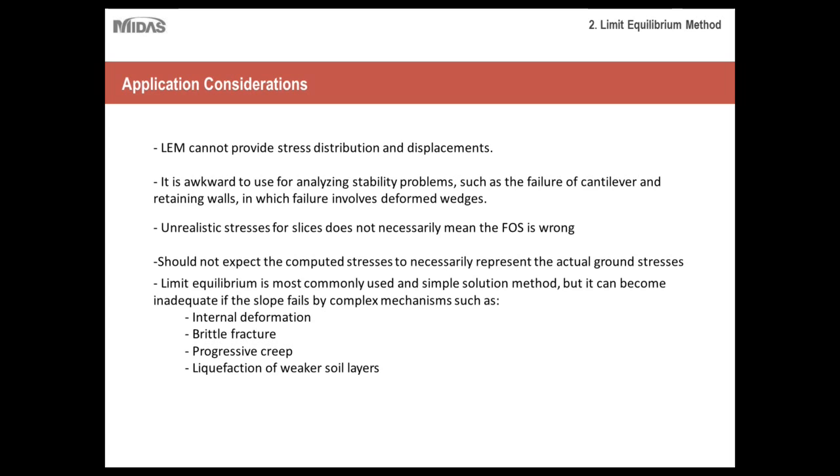But the main concept to grasp about the limit equilibrium method is that it's best suited for smaller scale, or not necessarily smaller scale, but simpler projects that don't require complex failure mechanisms to be taken into account, as well as displacements or maybe large support structures. So if you have projects that are more straightforward, where you just need a factor of safety, and it's very simple as far as the materials that are involved, then the limit equilibrium method would be your most effective choice.